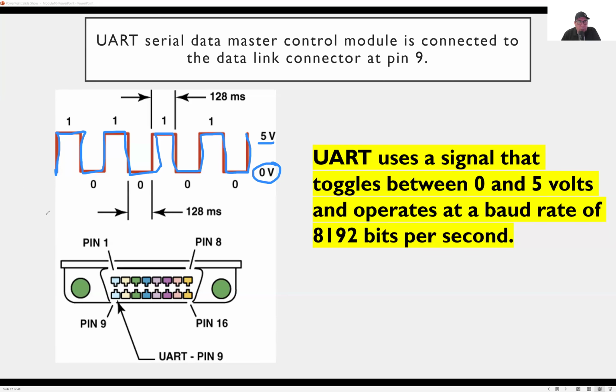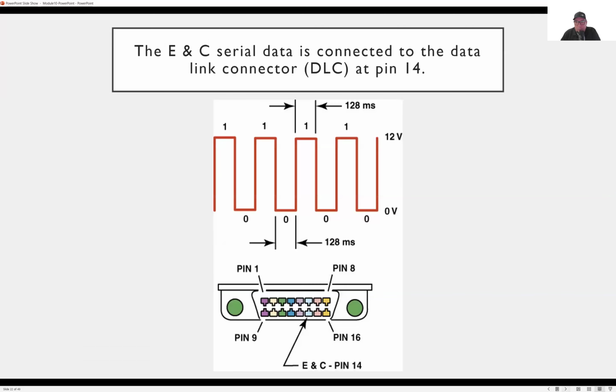Okay, if we can get everything done with 5 volts, with less voltage than we can with 12 volts, and we can still have everything work the same, then let's just use less voltage. It puts less stress on everything. If we're using less voltage to get the same job done, it's going to put less stress on our battery and our alternator and the rest of the network. We can have smaller wiring when we do this too and save money that way. So those are the reasons behind using 0 to 5 volts.